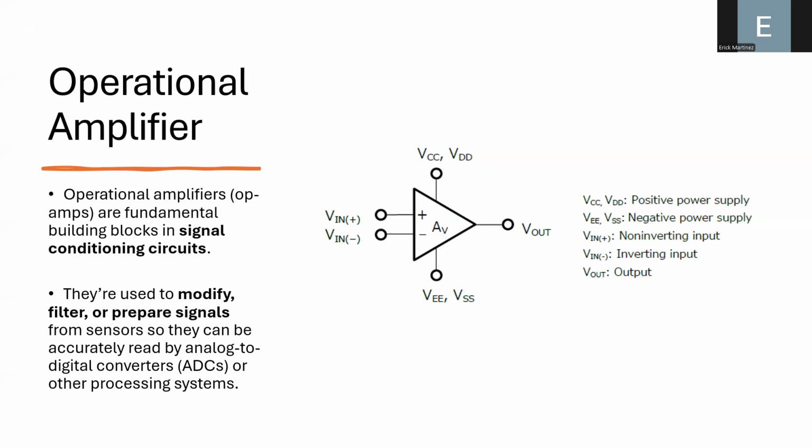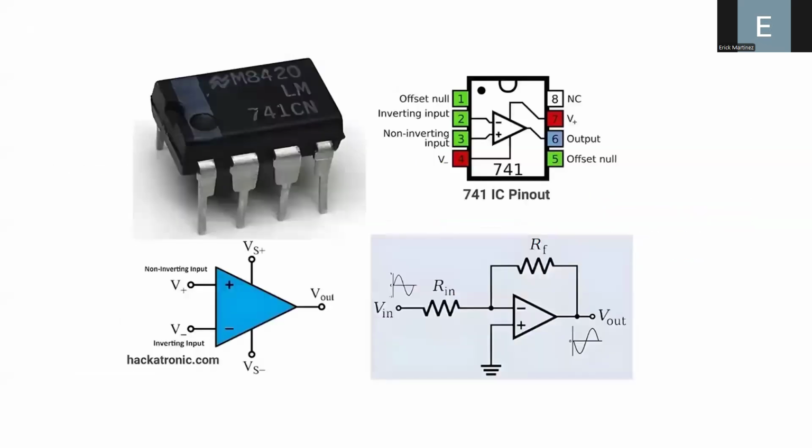operational amplifier, because the operational amplifier can perform many operations. Maybe we can add different signals, we can subtract different signals, we can even integrate or compute the derivative of the signal using this device. Or, you can see the effect of the amplification or the attenuation of the input signal, okay? And also you can generate filters. In particular, if you design an electronic filter to remove the noise, it's called an active filter, okay?